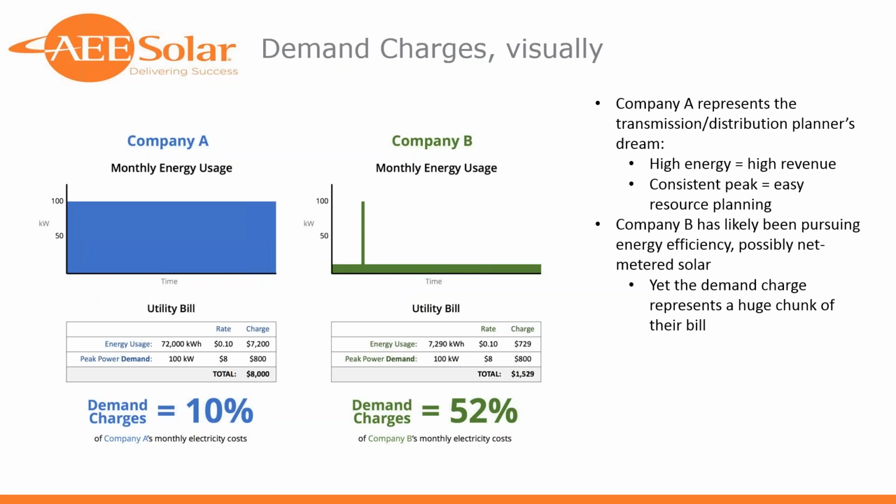lot of energy efficiency, perhaps has solar, but they've got one period in the month where, worst case scenario, it looks like all the loads happen to turn on and run at once. Other than that, they were a very conservative customer. You see here, for somebody like this, your traditional net metered solar system is going to do a lot to address their energy usage, but it's going to do nothing to address their demand charges.